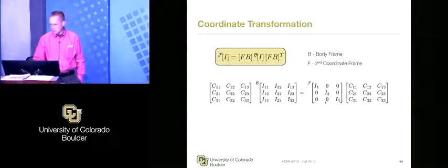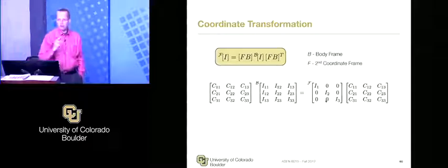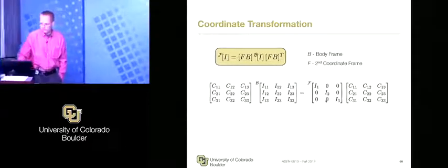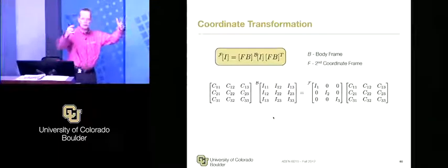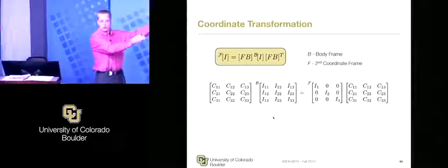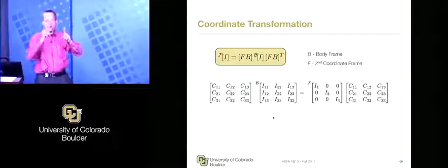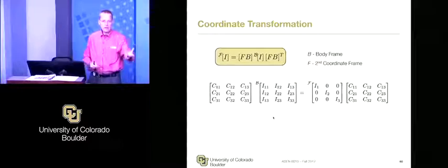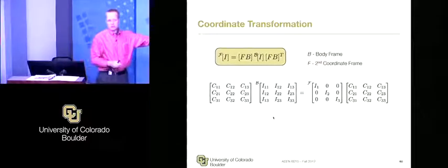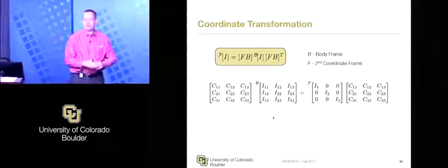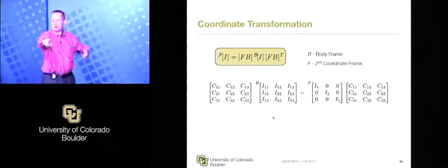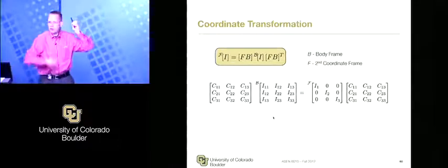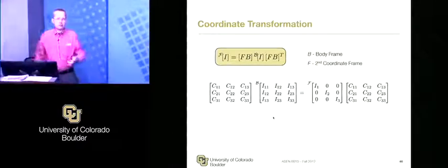That's correct. But the F1, 2, and 3 axes that you have to pick end up being the eigenvectors of this inertia tensor. So you go to MATLAB, plug in the 3 by 3, you get the 3 eigenvalues. Those are the 3 things. And then you get associated eigenvectors. Now again, here this ambiguity comes in. If I have eigenvectors, MATLAB has no idea what problem you're trying to solve. It doesn't know that classically the one axis goes to the nose of an aircraft, right? There's some algorithm that'll point the 1 to either be the right wing or top or up or down or forwards or backwards. It has no idea.